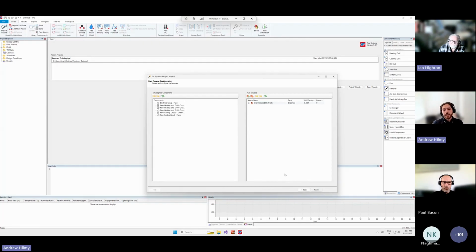Yeah, exactly. So you can actually specify PV based just on the area and the inclination and orientation, but that won't take into consideration self-shading from the building itself or surrounding buildings. Whereas if you draw it as a surface in the 3D modeler, you get all that shading information across, so you get a much more accurate result.